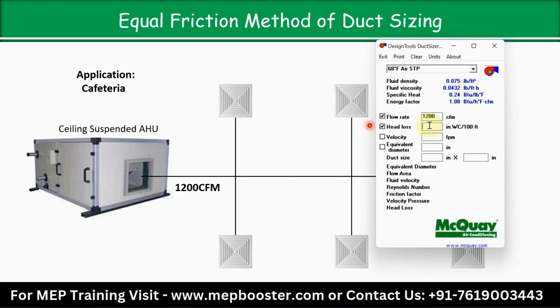That much friction loss we have to maintain. So at every 100 feet of duct length we have to cap the friction at 0.08. You can also select 0.1, no problem, but here I am designing for 0.08 because I want the noise level a little bit down. But see, this application is a cafeteria. In a cafeteria you can go for 0.1 also, no problem.